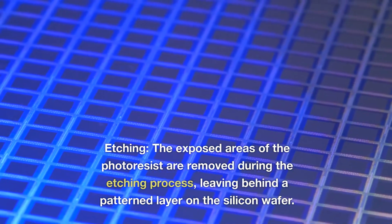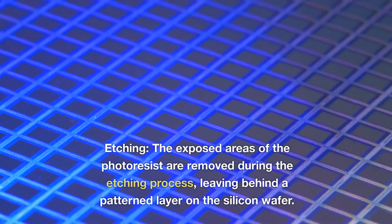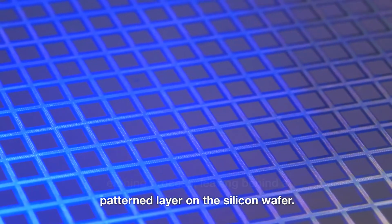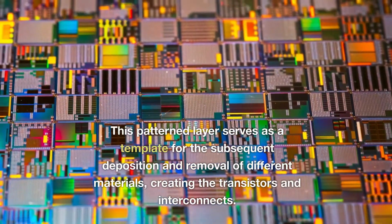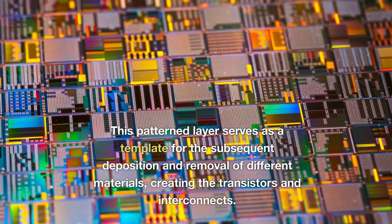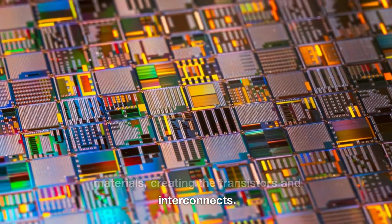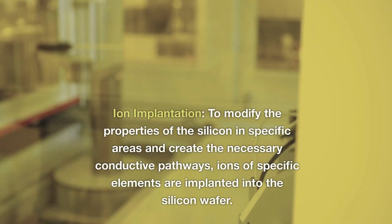Etching. The exposed areas of the photoresist are removed during the etching process, leaving behind a patterned layer on the silicon wafer. This patterned layer serves as a template for the subsequent deposition and removal of different materials, creating the transistors and interconnects.